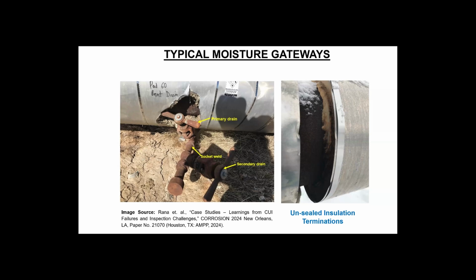So that is something we call field retrofitting triggered errors, or it could be the result of improper dimensions between the handle of the drain valve, or the swing radius not being accounted for, and the mismatch between swing radius and insulation thickness. So we can give it multiple names. That's a typical example of field retrofitting that is causing some damage to the insulation.